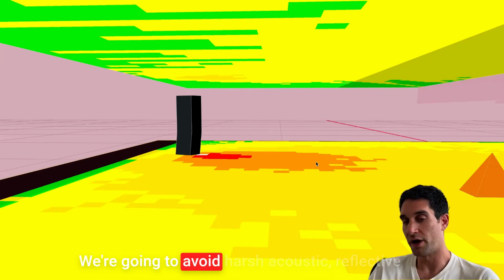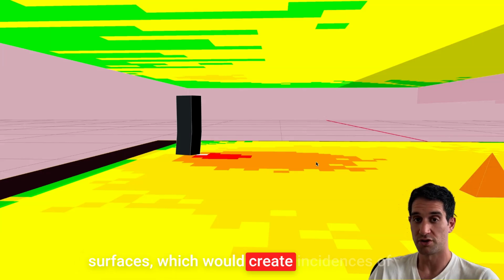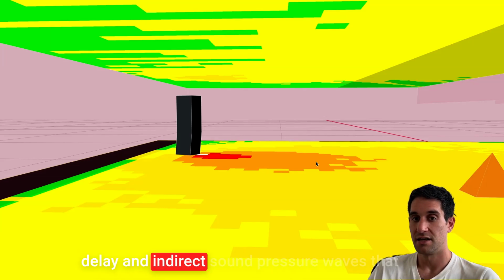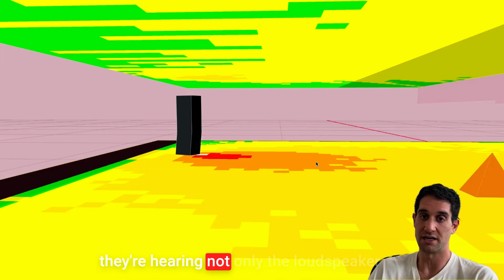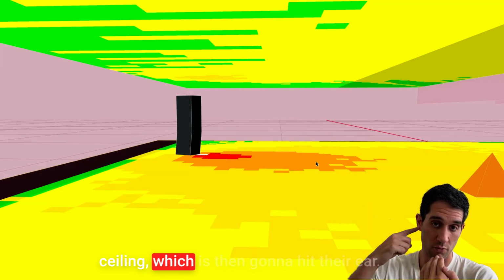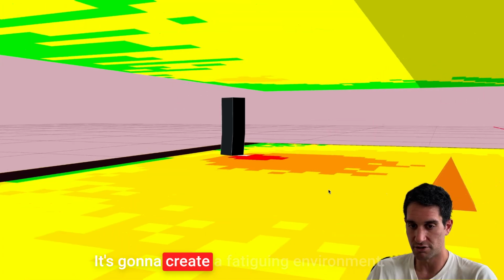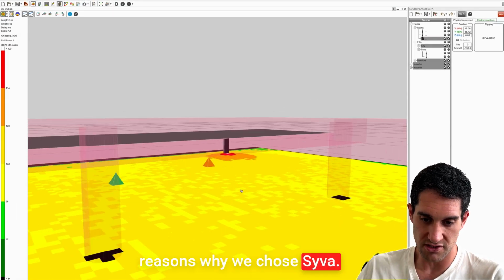We're going to avoid harsh acoustic reflective surfaces, which would create incidences of delay and indirect sound pressure waves that are reaching the audience's ears, because they're hearing not only the loudspeaker directly, but almost immediately thereafter, they're going to hear the reflection from the ceiling, which is then going to hit their ear. That's not going to make anyone happy. It's going to create a fatiguing environment. So that's one of the primary reasons why we chose Syva.